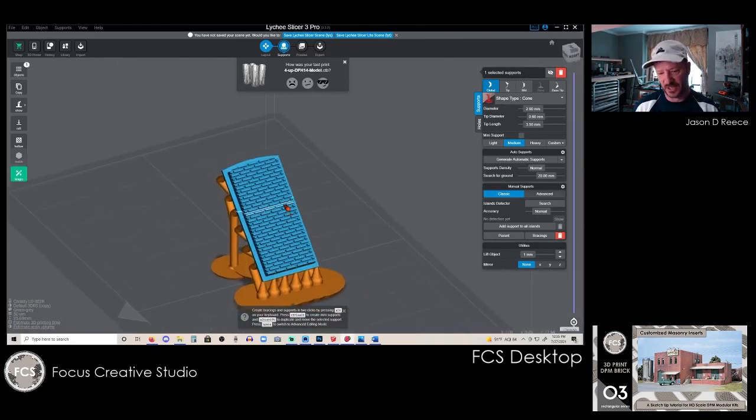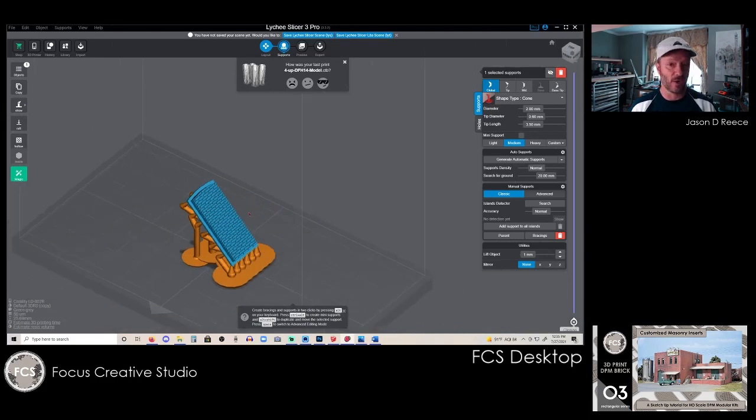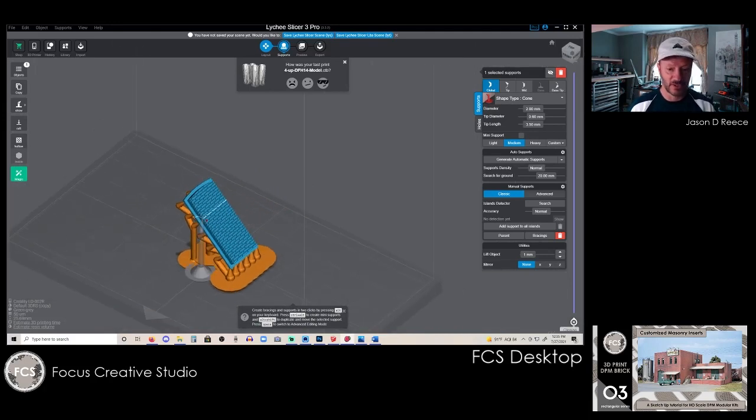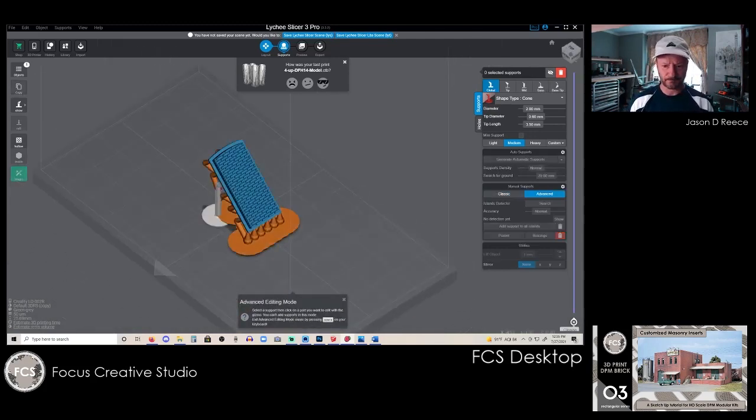And that's the key, is figuring out how many you need across the bottom. More is better. Guys, it's not worth trying to skimp on your supports. The resin amount isn't significant enough, and while this looks like there's certainly more resin in the supports than there is in the brick model, I'd rather them all be successful than have them fail. It's not worth it to me to try and see how thin I can get supports and have things still work. I've got a system, this works. You can see what my medium supports are. Go back in the video, see where I have my heavy supports, but this basically takes care of supports.